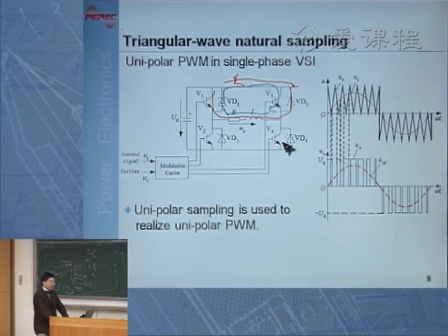Okay, and therefore the right-hand side of the load will always be connected to this point. So whether the load will see positive voltage or zero voltage will depend on whether you are sending a turning on signal to V1 or a turning off signal to V1.